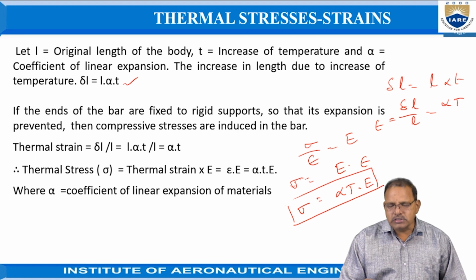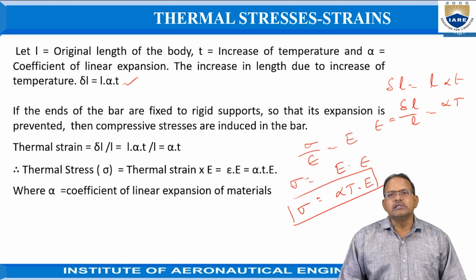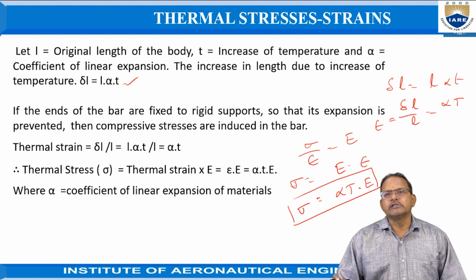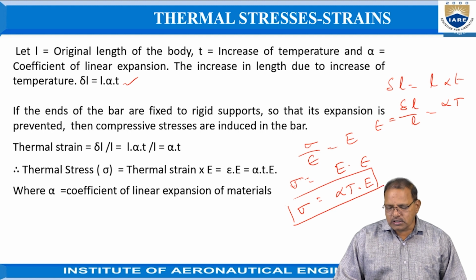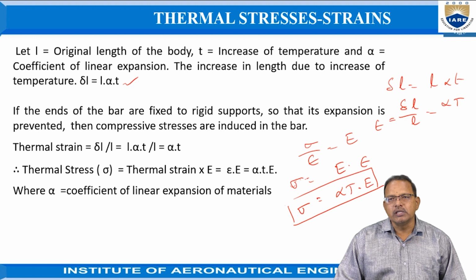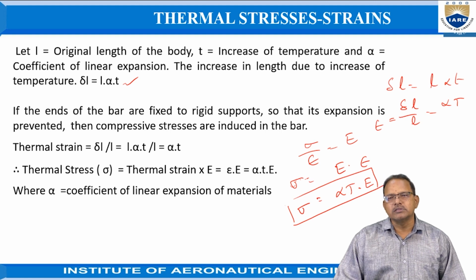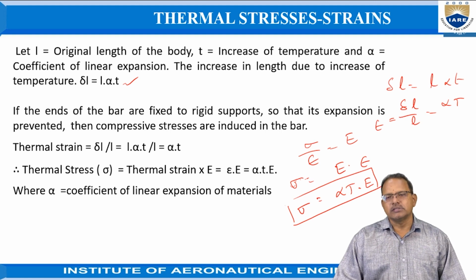Hence, these stresses are called thermal stresses. When the expansion is prevented, the thermal stresses produced are compressive in nature. When the temperature decreases, the supports do not allow contraction, hence tensile stresses are produced in it.